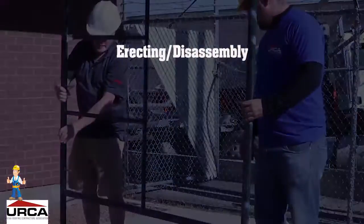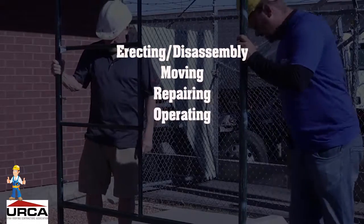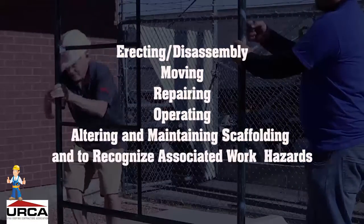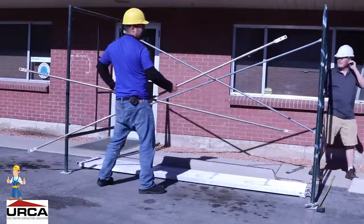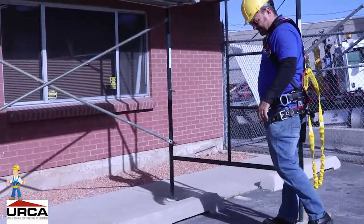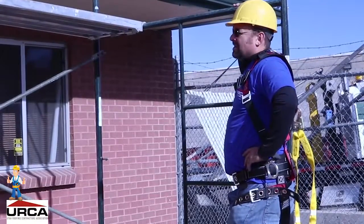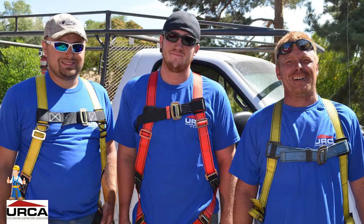They train employees in erecting or disassembly, moving, repairing, operating, altering, and maintaining scaffolding, and to recognize associated work hazards. They select and direct erectors or qualified workers to conduct work on scaffolds, and they determine the feasibility of fall protection. Ultimately, they determine when and if it is safe to work on or to use a scaffold. They ensure that every worker on a scaffold has and uses a PFAS when required.